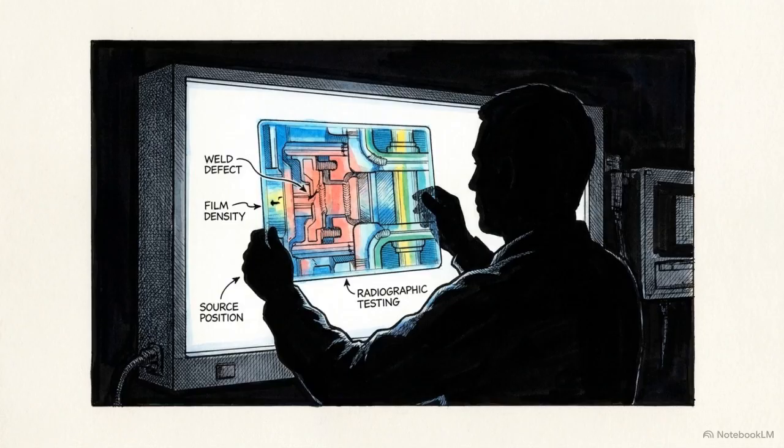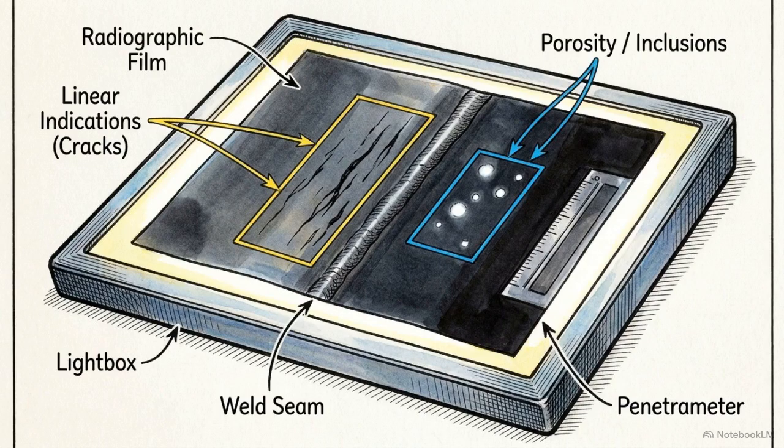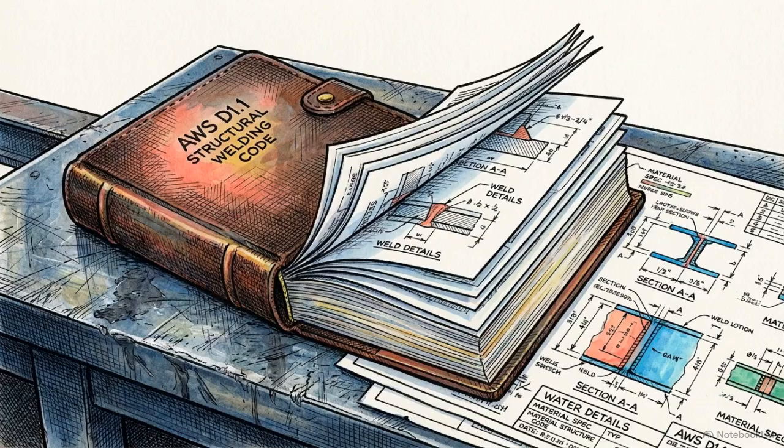While VT limits surface traps, radiographic testing reveals the internal reality. On RT film, slag appears as dark, irregular lines called wagon tracks, contrasting with the bright white circular spots that indicate tungsten inclusions. These AWS code limits represent a direct mathematical translation of fatigue mechanics into field-measurable tolerances.